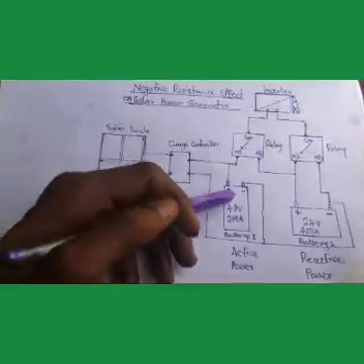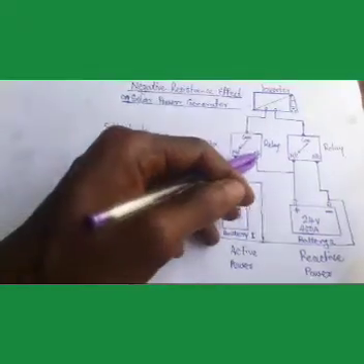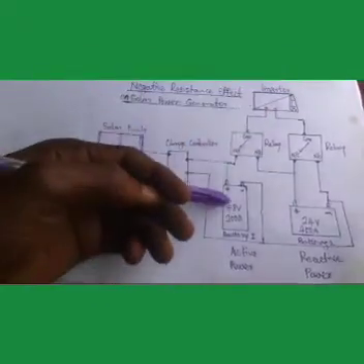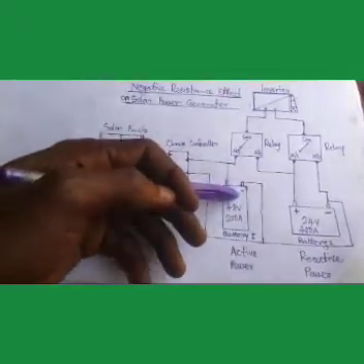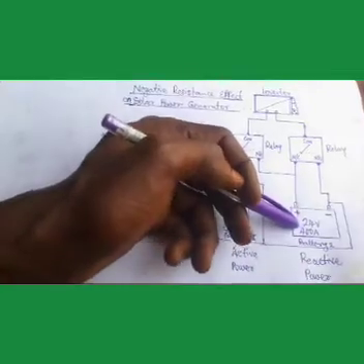Now as soon as this one is drained, you can go back to the first one, which means disconnecting the triggering relays and allowing the inverter to automatically consume the energy from this. While you are consuming this energy, the second battery is being charged.